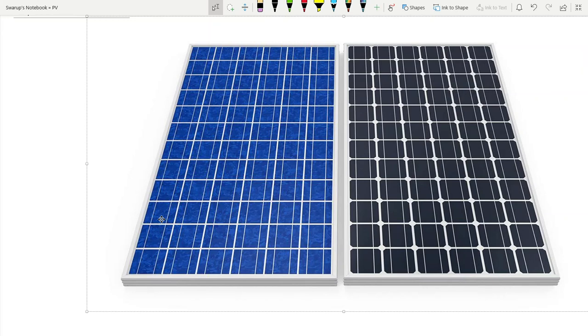You have come across different types of material, single crystalline material and polycrystalline material. Polycrystalline material is made up of very tiny single crystals, and that's why it's called polycrystalline. Each single crystal has grain boundaries, and there will be some scattering of light at the grain boundaries because there is a sudden abrupt change in the crystal orientation at the boundary.